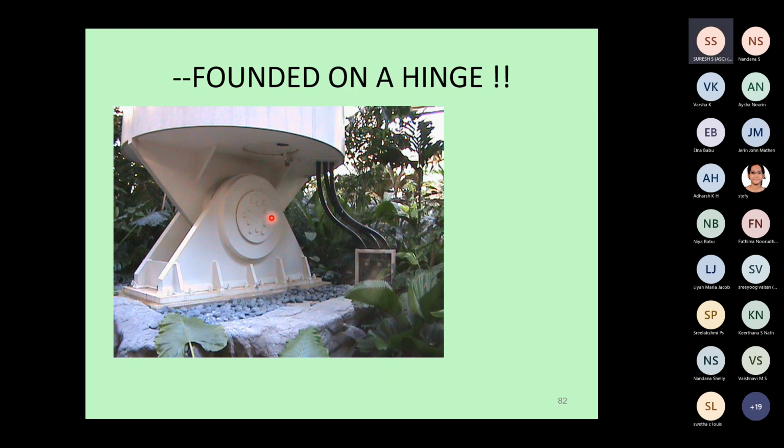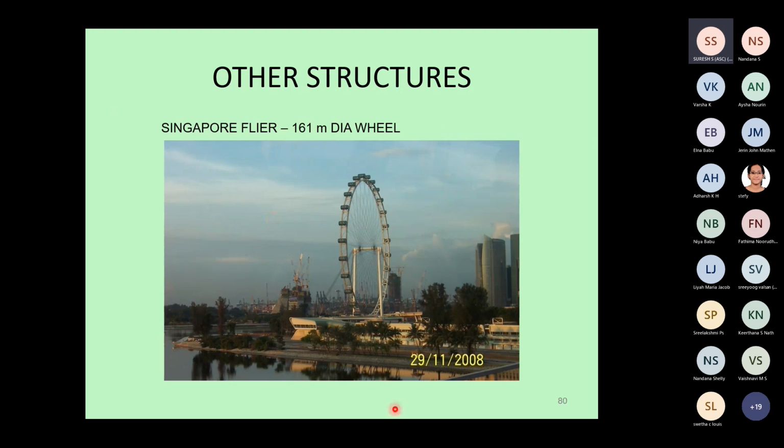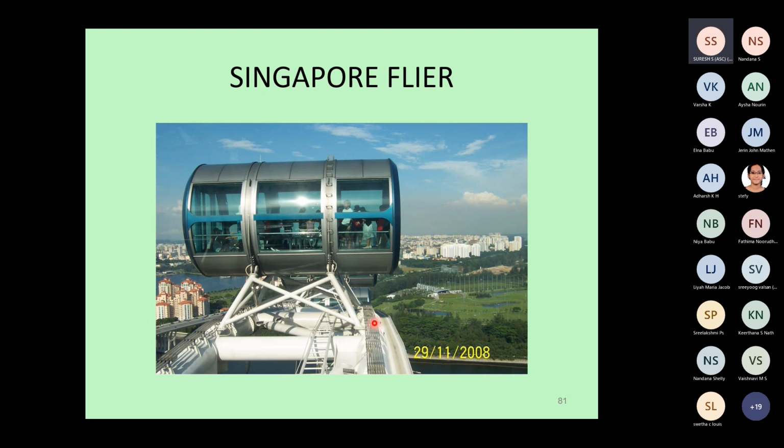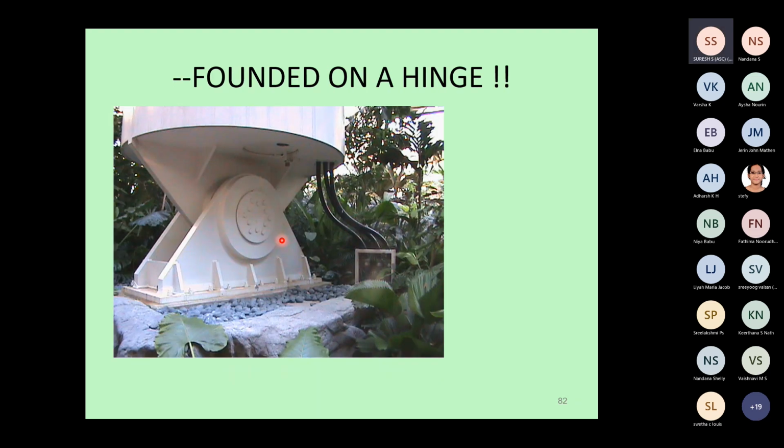So its bottom point, this point which I am showing you, that photograph is of the bottom part of this vertical column. Bottom is hinged. They are hinged for several things. One, any support settlement or deflection behavior, to avoid excessive moments. Also to make sure your analysis, design, assumptions in the analysis, design and construction match.